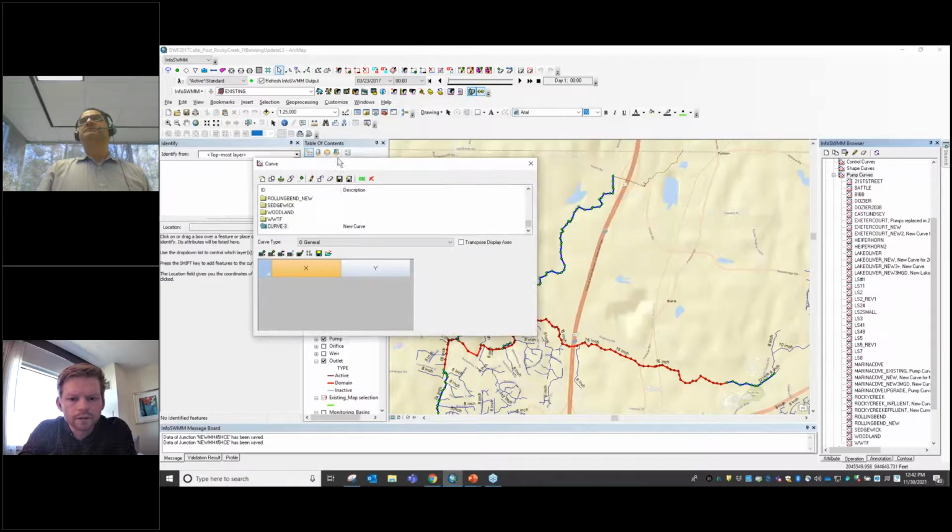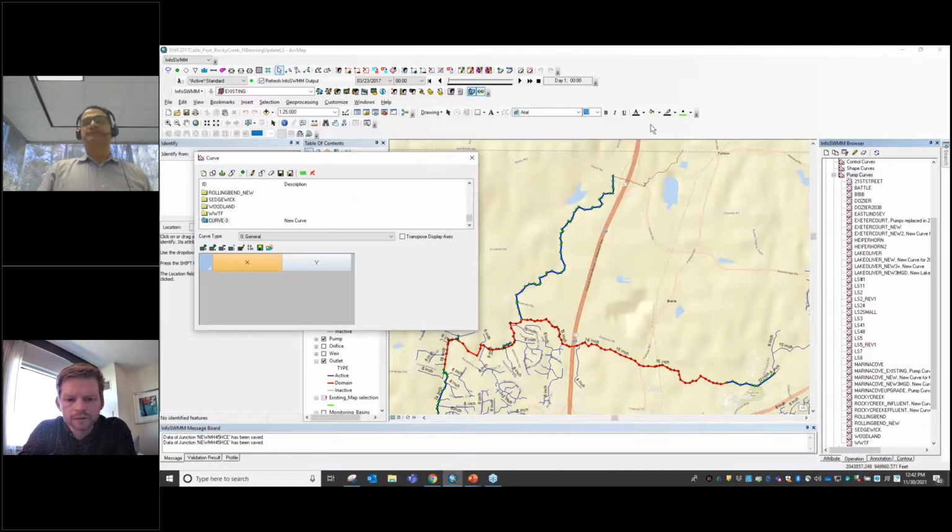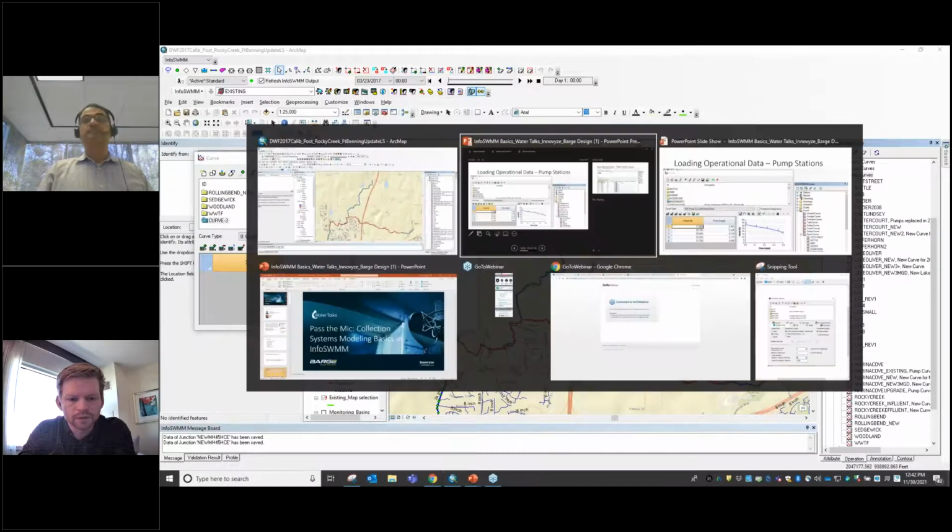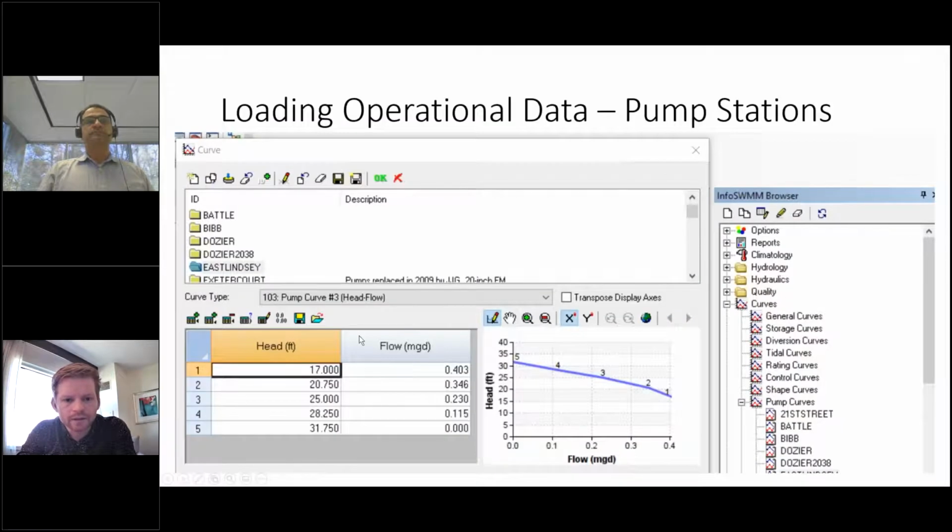Yeah, and I'm looking at the help menu, and it's saying the type 2, the 102, is an inline pump where flow increases incrementally with inlet node depth, and that the type 4 is a variable speed inline pump where flow varies continuously with the inlet node. So hopefully that answers that question. And underneath the pumps in the help menu, there is a little more detail on that.